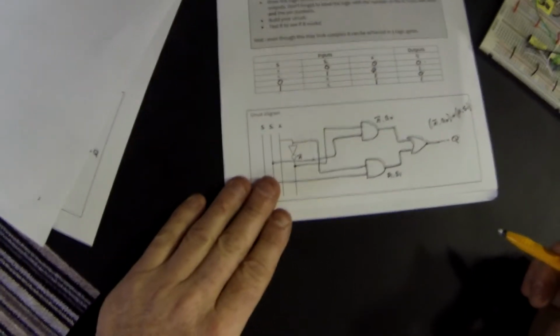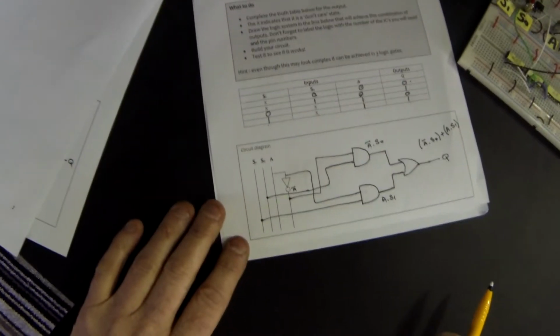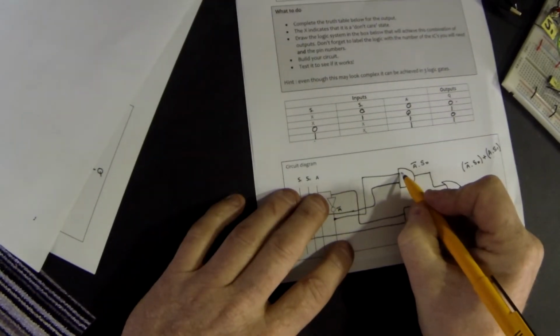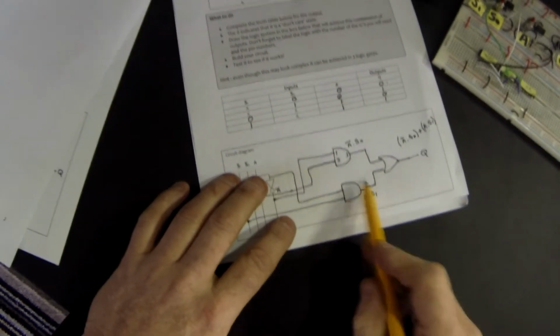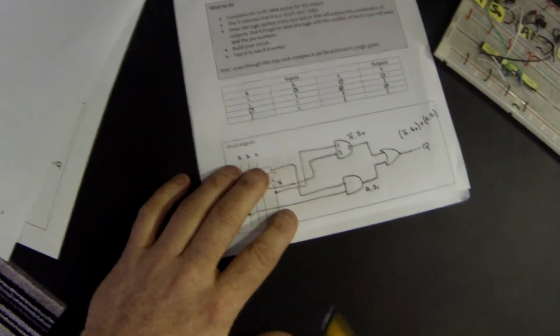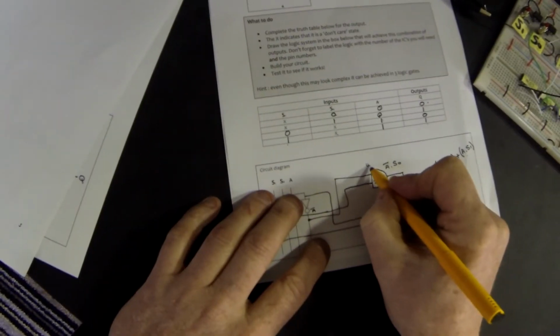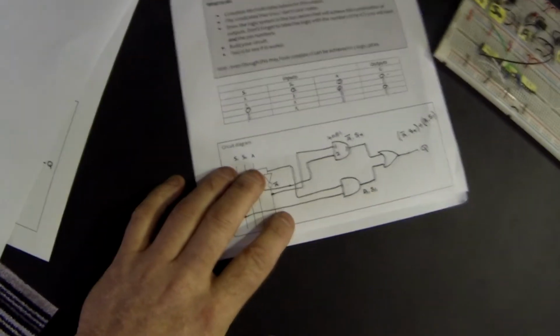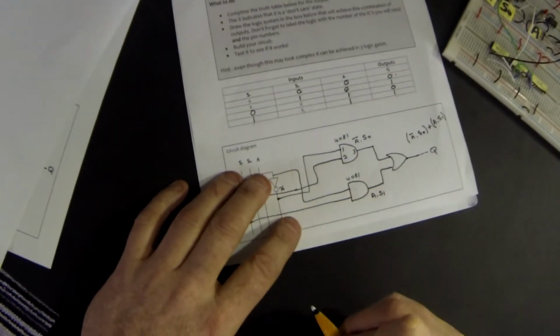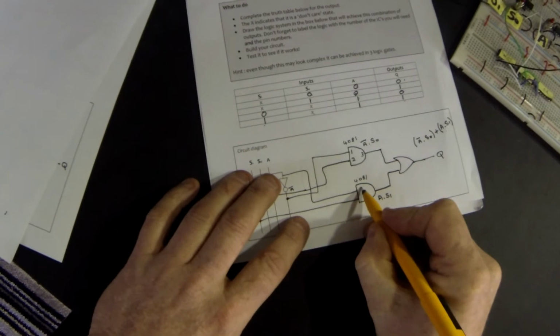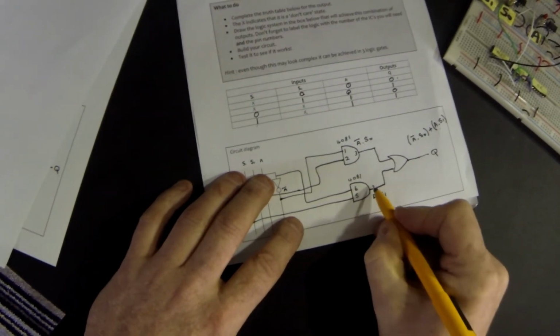So there we go. We have our circuit. All that's left now is to label all our pins. So 1, 2, 3. Now the problem is here we're using a second logic gate, so we have to use the second one in the chip, and we know that this is a 4081. So this is the 4081 as well, and the same one, but now we have to use different pins. So we're going to use pins 6, 5 and 4.